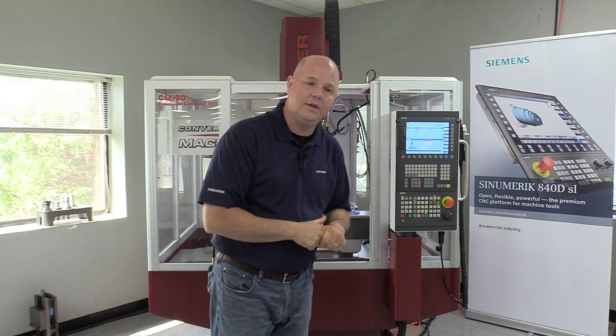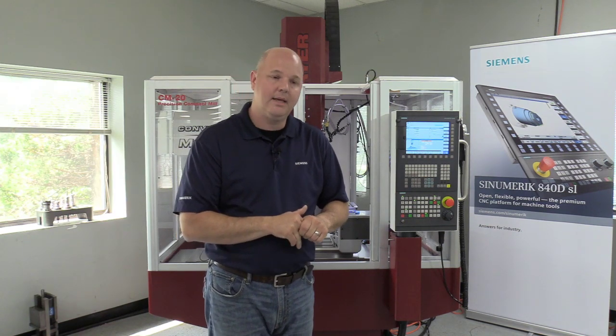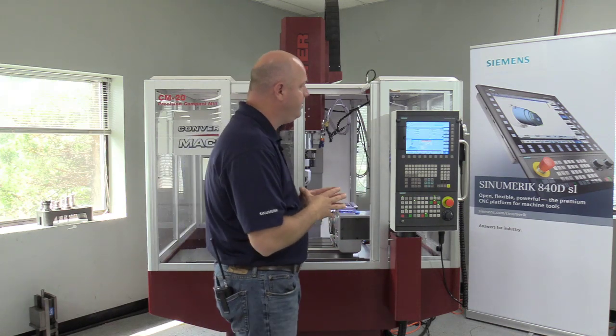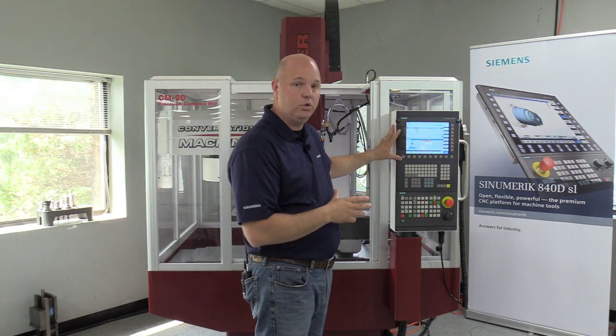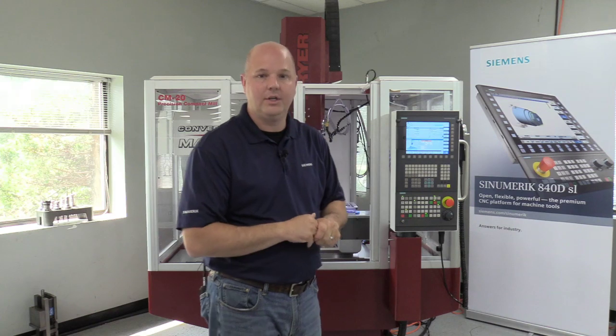Another comment. So it was a good question or a good point from one of my colleagues. When building an archive, it is always good to have a clear spindle when you make that backup. Some machine OEMs are much more critical on that than others. So what you would want to do is do a tool 0 to clear the spindle before you actually make the archive like we showed you earlier with the Control-Alt-S functionality.